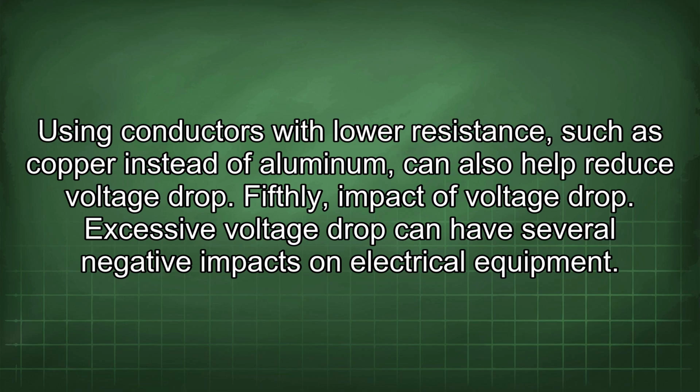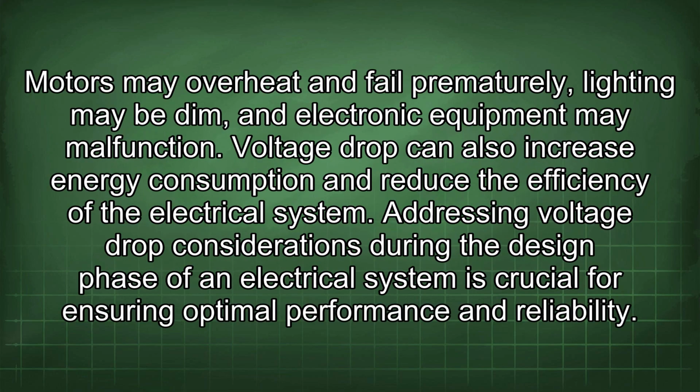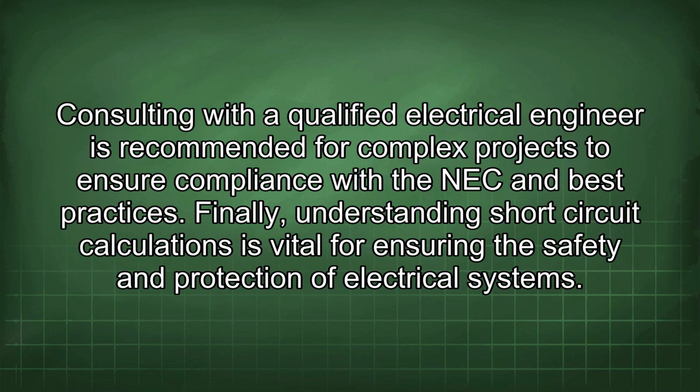Fifthly, impact of voltage drop. Excessive voltage drop can have several negative impacts on electrical equipment. Motors may overheat and fail prematurely, lighting may be dim, and electronic equipment may malfunction. Voltage drop can also increase energy consumption and reduce the efficiency of the electrical system. Addressing voltage drop considerations during the design phase of an electrical system is crucial for ensuring optimal performance and reliability. Consulting with a qualified electrical engineer is recommended for complex projects to ensure compliance with the NEC and best practices.